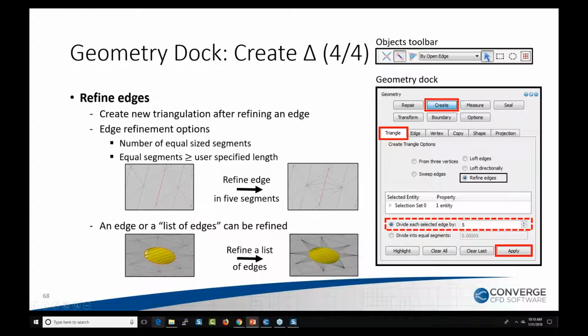It is going to just create triangles on straight sections, or more refinement on straight sections. So don't use this if you want to create a smoother curvature. This is only to create more triangles. So sometimes it's useful if you want to use that as a precursor to more advanced geometry operations.